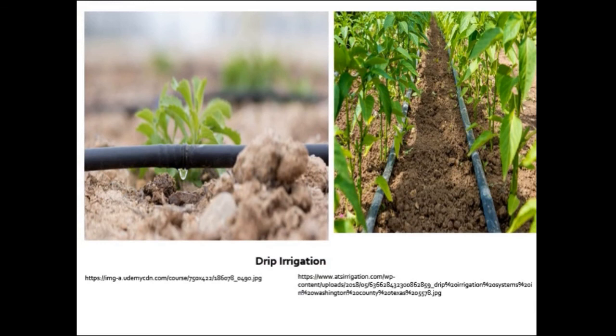One of the main characteristics of this method is point irrigation as compared to area irrigation with sprinkler or flood irrigation. A network of laterals supplies the water and fertilizer to the plant roots. Water is generally discharged at a very low rate, in the order of 1 to 2 liters per hour, although high rates up to 8 liters per hour or more can be achieved using special drippers.